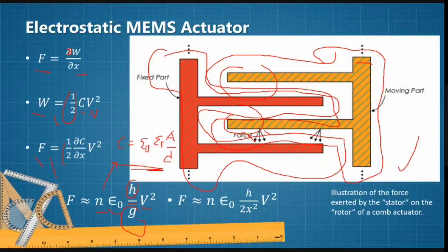The force is proportional to the square of the applied voltage between the fixed comb and the movable comb. We have to remember that the force doesn't depend on the displacement x. That is, the force is always the same throughout the travel of the movable comb.